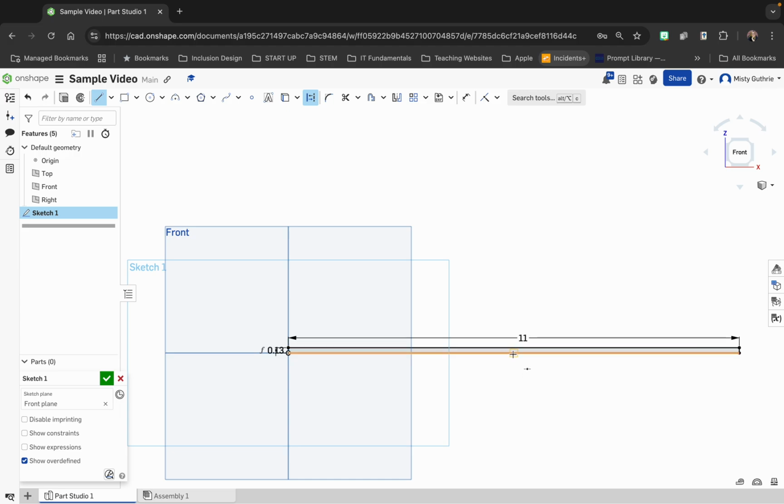And you can see those little yellowish orange boxes that are forming. I'm going to click that and go straight up. The maximum height of my bridge is 4 inches from top to bottom. If you include a substructure, which is a smaller structure underneath the bridge, you may want to keep in mind to keep the top part a little shorter. So I think I will model it that way, and I'll keep this top part 3 inches.